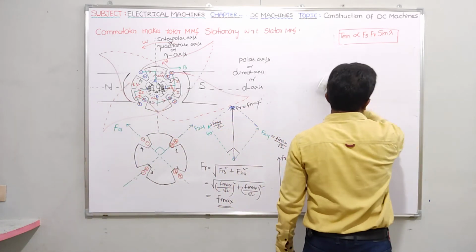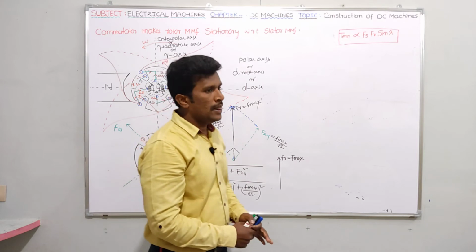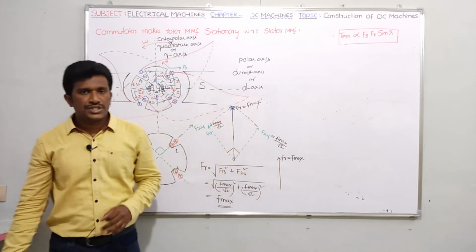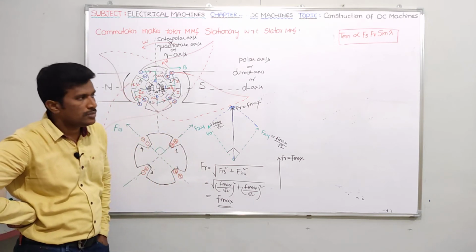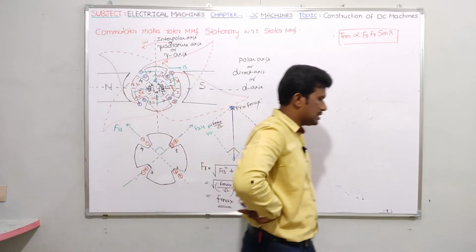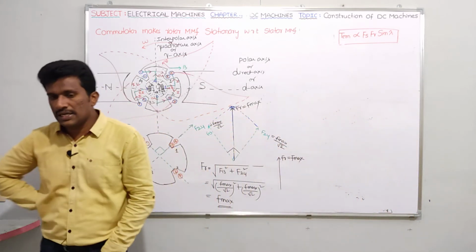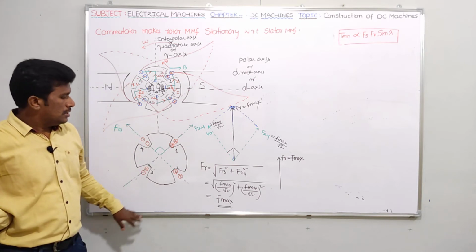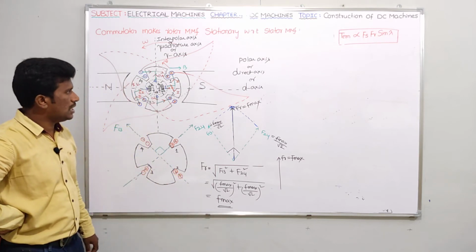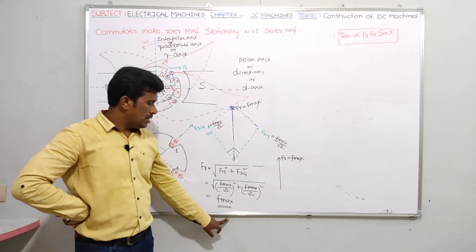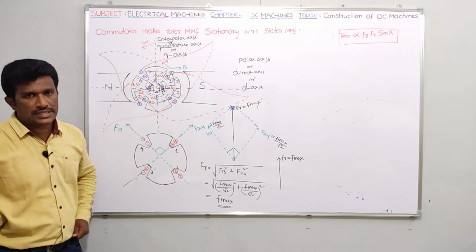Practically anyway, regarding this we'll discuss clearly in the next video, where we'll be discussing brushes. Okay, just simply note down one point. Practically, brushes are placed along the direct axis, comma, but in general, since the commutator is not shown, brushes will be shown along the Q axis.